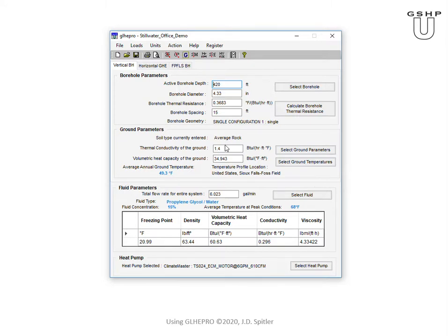The thermal conductivity of the ground that we measured, and I say we measured it, we did a rough estimation based on this thermal response test. And we got a thermal conductivity of 2.8 watts per meter K, and that's about 1.62 BTUs per hour per foot degree Fahrenheit. The volumetric capacity that we estimated, if you translate to IP units, it's 37.277.